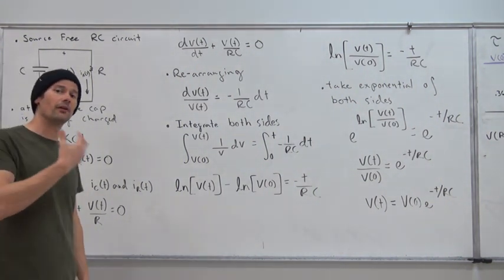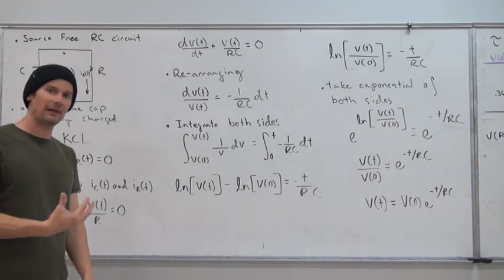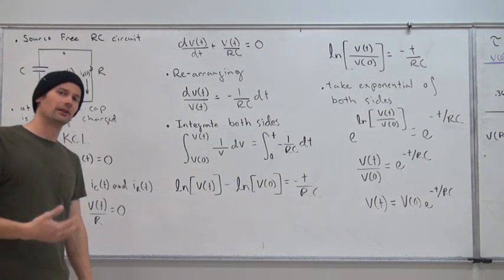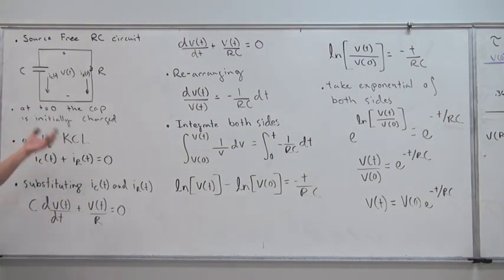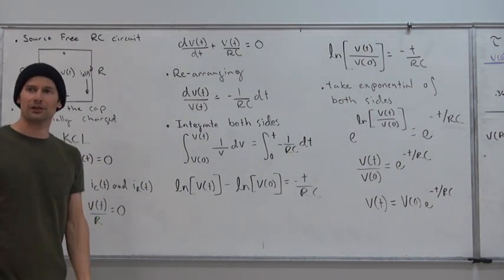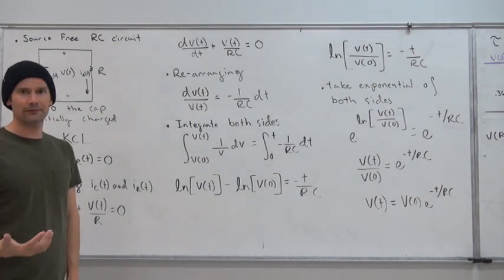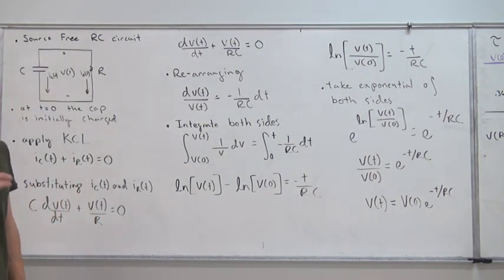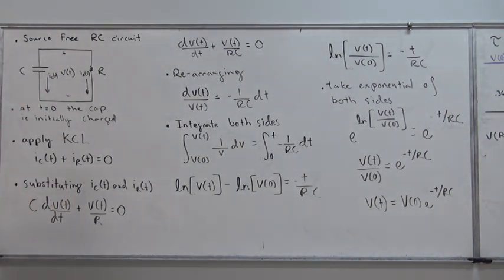But what we're doing is dumping all that energy. We're allowing the capacitor to dissipate that energy through a resistive element, which in this case is going to be our flash. Usually with a capacitor, we can say whether it has an initial condition for the voltage across it. Sometimes we have an initial voltage, sometimes we don't. In the camera flash example, sure enough, there is a voltage that we store across those two plates. So let's see if we can determine a solution for this differential equation and determine what the voltage is across this element.